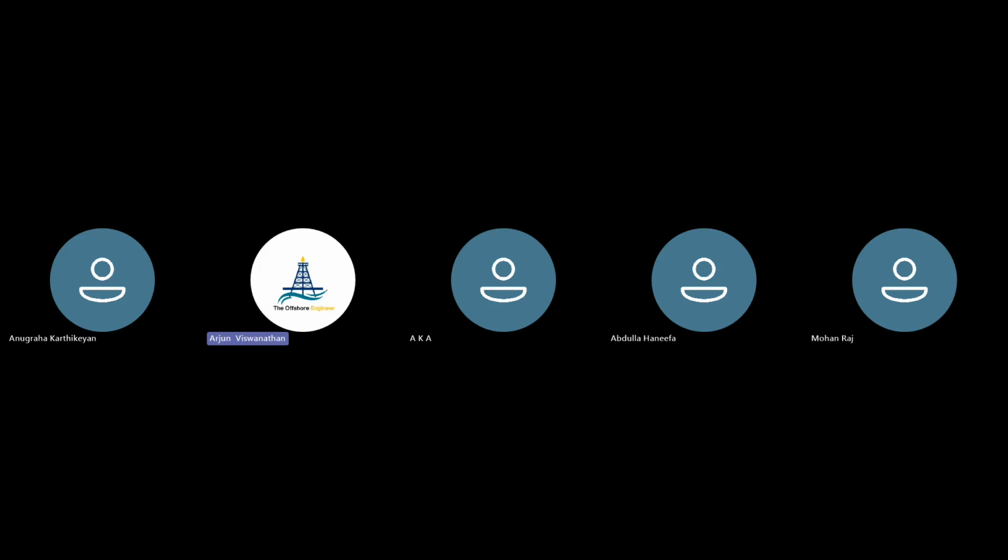So if the DAF is more, and if we are not able to do that installation, what people used to do is they used to add some extra weight called clump weight. The clump weights will add some extra weight to make sure that the structure doesn't behave violently, and the dynamic amplification factor value will come down. So in that case, we can reduce. That's the justification I got when I checked with API and DNV.